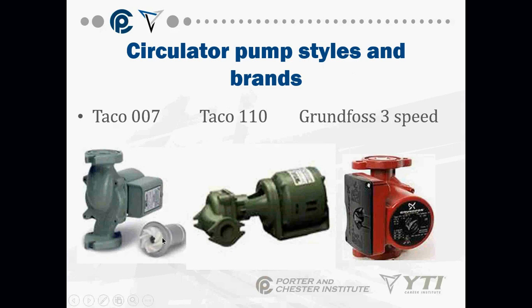This actually will come out, and you can replace it if it happens to become damaged in any sort of way. Usually these will have two ball valves located here and here. So if this happens to actually fail, the motor fails, what have you, you can just close those two ball valves, and you can remove these pumps entirely without having to drain the entire boiler of water. So they are actually pretty